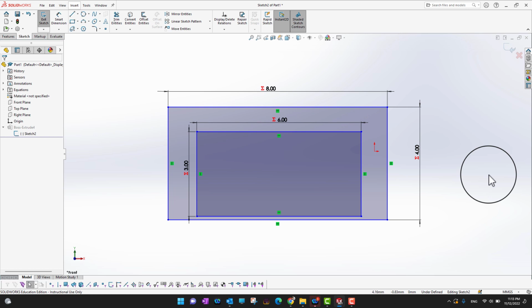If you have a big sketch or you have a big body and you have multiple holes, and later on if you want to advance, or if you want to change the value of a single hole, what you need to do, if you already made those multiple holes in your body by using global variables, is, if it was a half-inch hole or if it was a 1-inch hole and you want to modify the values, you just need to change the value in the global variables, and then it's going to change the whole body's holes according to your global variable.